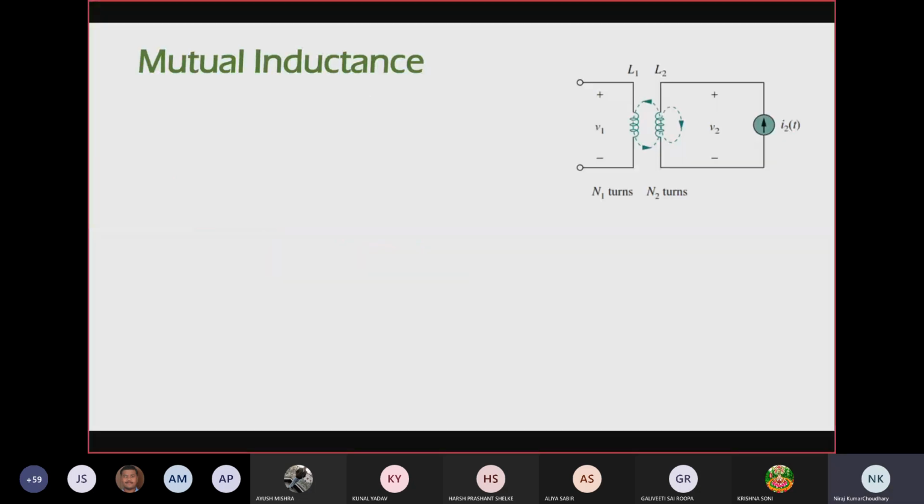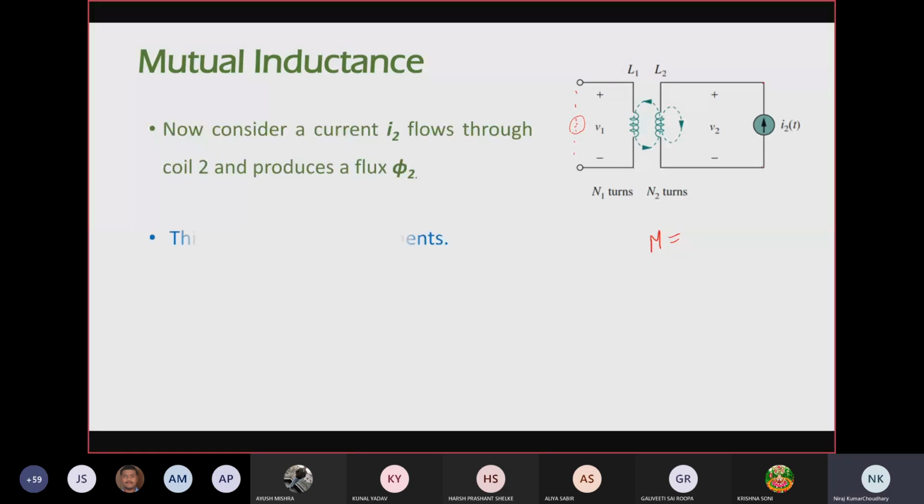or conductor. So similarly, second thing, in this way also you can assume, कि जैसे अभी फर्स्ट केस में हम लोगों ने क्या कंसीडर किया, we have excited the first coil with the help of a voltage source. Now alternately you can excite the second coil and you can estimate or calculate the expression of the mutual inductance here. तो इस केस में भी तुम कर सकते हो कि mutual inductance कितना होगा when we are exciting the second coil, right? The process will again remain the same, there is nothing new here.